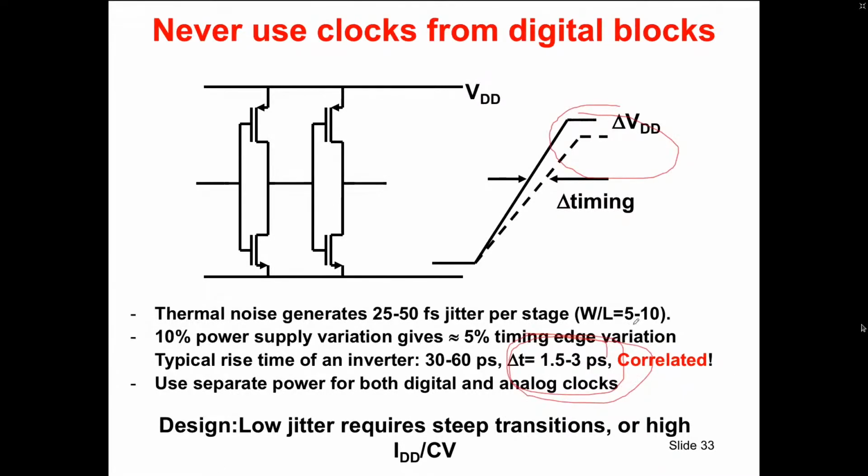So whenever I see a problem in jitter, my first point of attack is that I want to see how clean is the power supply, and aren't you running into real trouble over there? And you won't believe how often I see that people push clocks for A to D converters, for switch cap circuitry, for class D amplifiers or whatever more, through the digital block over there.